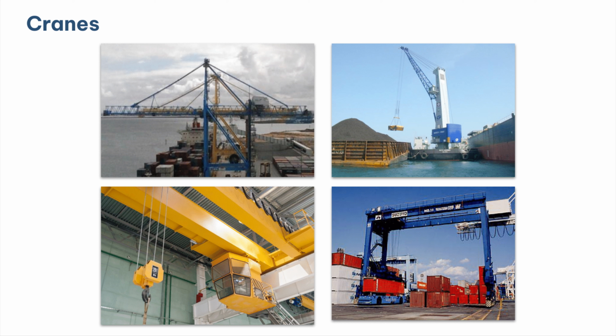Cranes are another one that a wired online system is the way to go. They are constantly changing direction, speed, state, and load, and you can take all that data into your online system and you can accurately trend the data. A wireless system will have trouble with the start and stop nature of the crane and also the changing speeds and loads while it's taking data. So you will have trouble with accurate trending data.